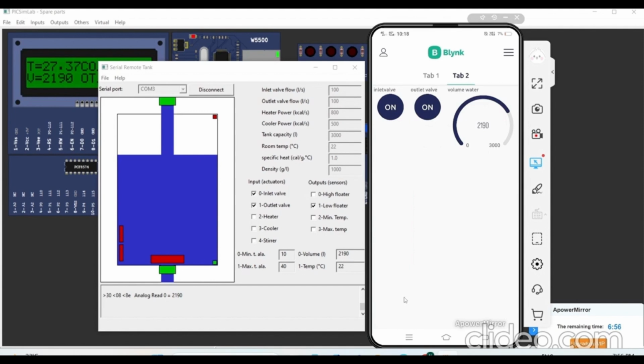For garden lights, we used an LDR sensor to continuously sense the surrounding light's intensity and adjust the brightness of the LED accordingly, ensuring lights remain bright when there is low sunlight and dim or turned off during daytime, which directly contributes to energy conservation. For our temperature control subsystem, we used an LM35 sensor to monitor real-time temperature values displayed on both the CLCD and the Blynk gauge widget to manage the home environment effectively.